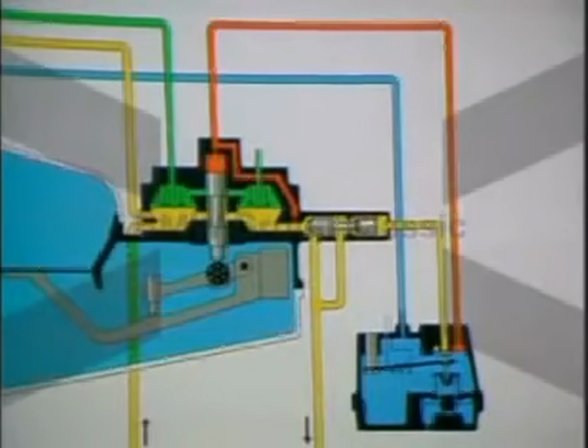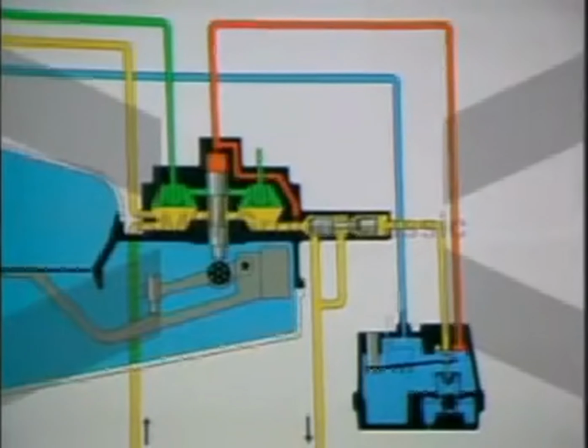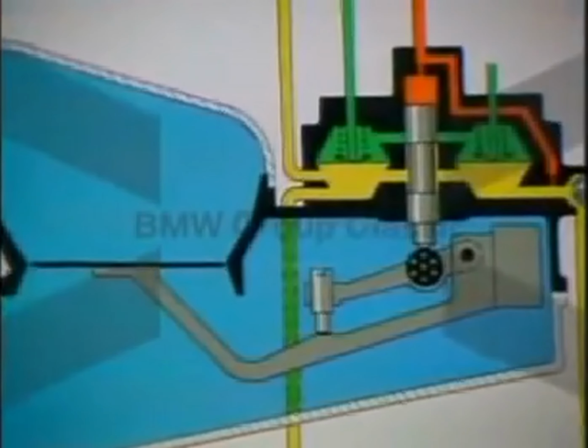The control pressure, formed above the control plunger, constitutes the opposing force to the air pressure acting on the sensor plate, which, in relation to the sensor plate's position, determines the actual composition of the mixture.